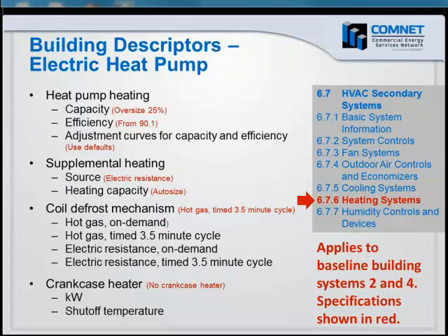One more question. As far as the pumping power, you indicated that you could use the pump per unit flow or the power per unit flow method. Is it allowable to use the detailed input method for the baseline building, or does the software have to accommodate? No, not for the baseline building. For the baseline building, you'd need to use the power per unit flow method, since that's not specified in Appendix G.